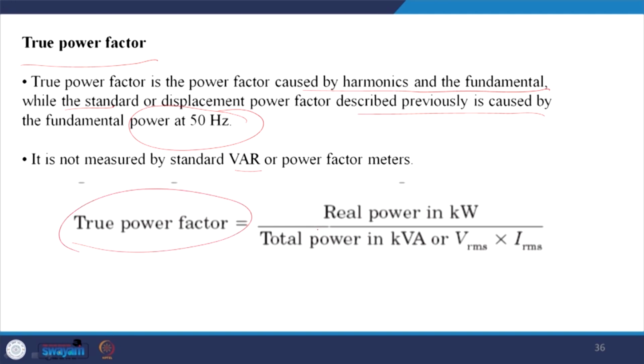For this reason, real power in kilowatt, that is what you are consuming, because if you multiply sin n omega t into sin m omega t and integrate over 0 to 2 pi and take the average over 2 pi, you can see that this power gives you 0. So, harmonic power, if you average it out, gives you a 0 value. But the problem lies in that once it flows through the resistance or other network, it loses power, which has to be accounted for somewhere.